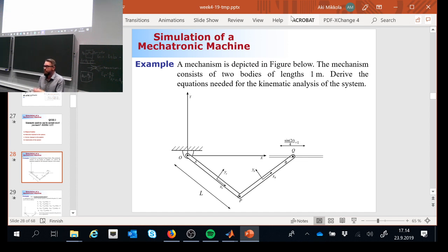In order to have a Jacobian matrix, we have to have the constraints. How can we express the constraints? Well, with the help of the equation that we are very much familiar with: r plus rotation matrix multiplied by vector u bar. By the way, it would be all right to make a tattoo of that equation because it's not going to change. We're going to keep on repeating that forever. It would be a good investment if you make a tattoo of that equation.